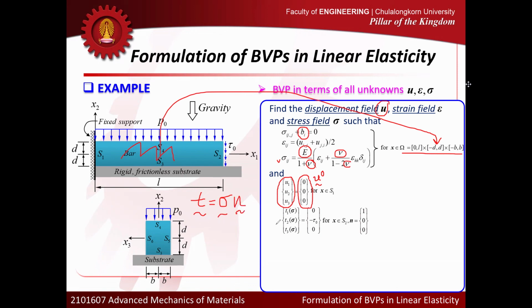So now if you write down the traction in terms of stress like this, using this relationship, you have a way to check this condition for the surface S2, right? So basically you just take stress multiplied by N and you verify with these quantities. And N for S2, I showed you before, right? For this surface, we know that N equal to 1, 0, and 0. So basically this is the way that allows you to check this condition.